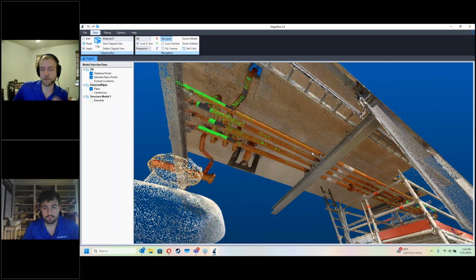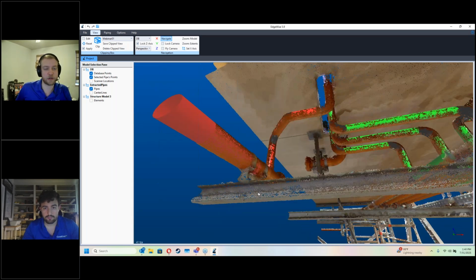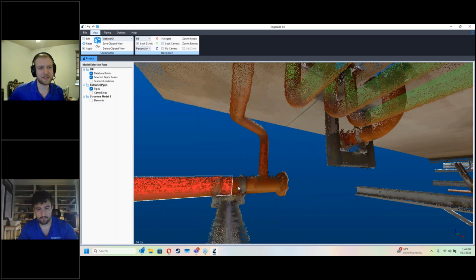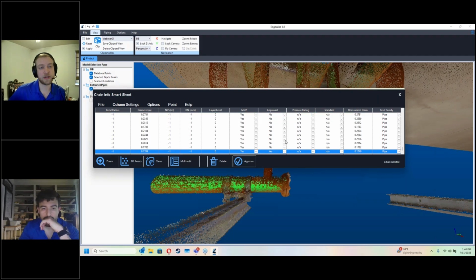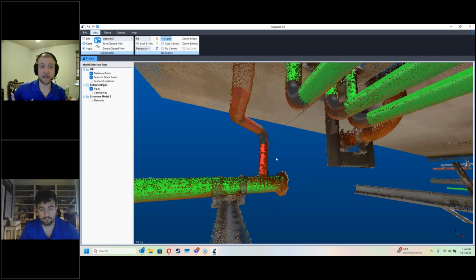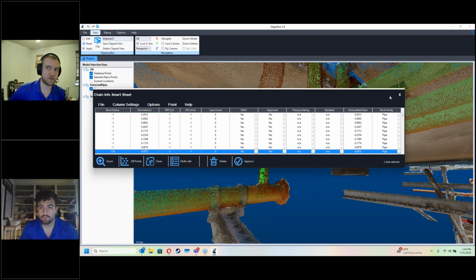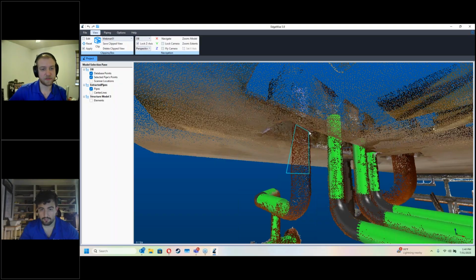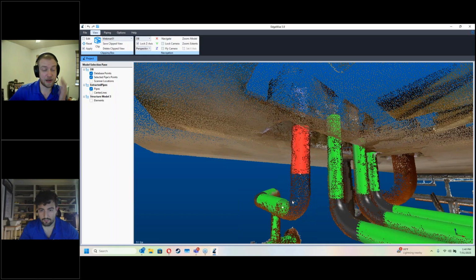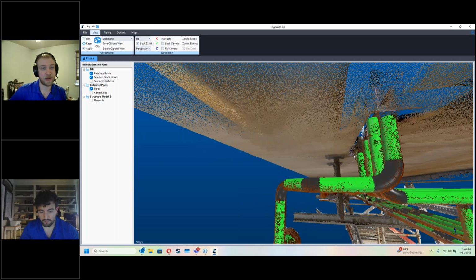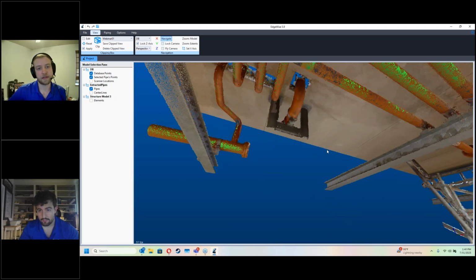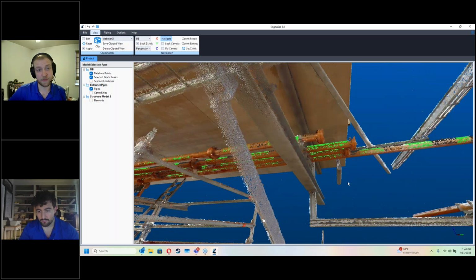We do have cable trays. Someone did ask about that. There's a whole module for cable trays that's very similar to structure and goes into Revit very nicely. Just to cover people who may not be as familiar with EdgeWise, we can do piping elements, and I'll focus on the Revit side for commonality. When we export to Revit, we can go as piping elements, as conduit electrical, and as round ducting through the piping module. There's also the ability to do structure, so that can do concrete and standard steel geometry.